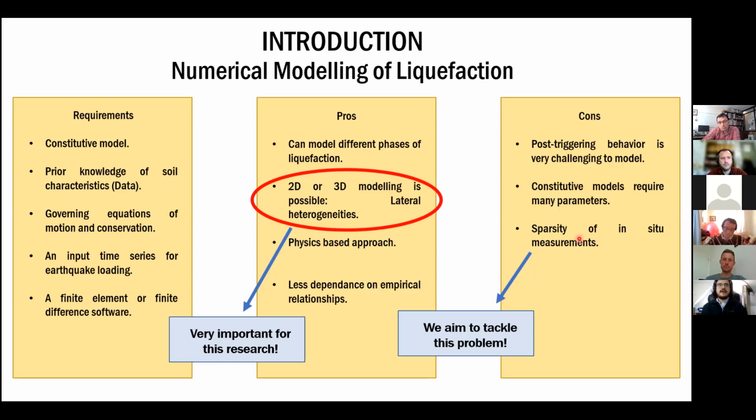And we obviously cannot do a very dense map of these tests because it's expensive and invasive to do. But here we are going to present a methodology by which we can get a 3D model with a lot of data by means of creating a shear wave velocity model.